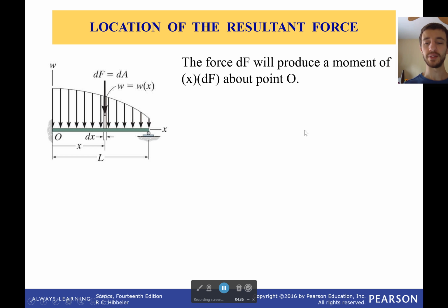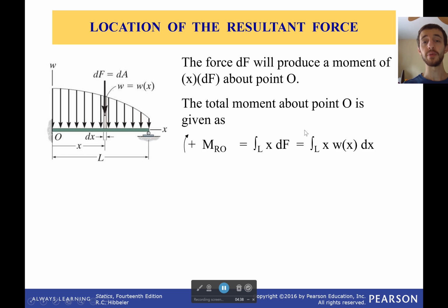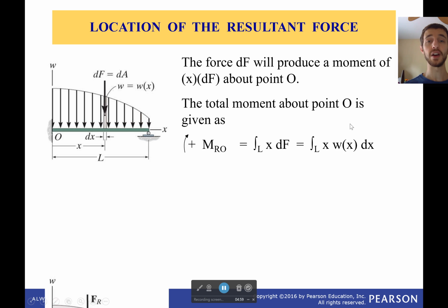So to get that, what we do is we first sum for the moments. Okay, we got to figure out the moment around this. What is our resultant moment due to this distributed load? And so that's going to be equal to a distance times the force. We've already said that that force right here, this little force element, is going to be equal to the loading times the change in position. So if we integrate this, we will get our